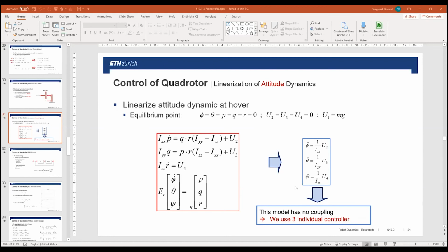So this describes the dynamic of the system, and you will control around, in hover, for example, around the 0 axis. So you have to calculate the forces generated by the propellers if you deviate, and how you can actually bring it back to hover or to 0 position.